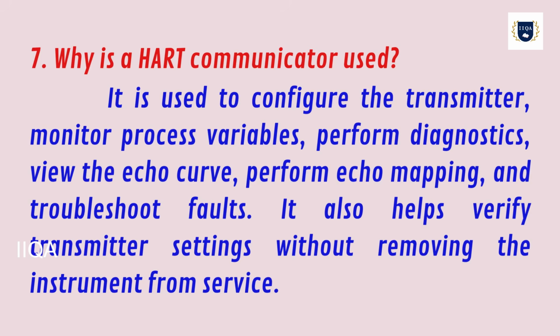Why is a HART communicator used? It is used to configure the transmitter, monitor process variables, perform diagnostics, view the echo curve, perform echo mapping, and troubleshoot faults. It also helps verify transmitter settings without removing the instrument from service.